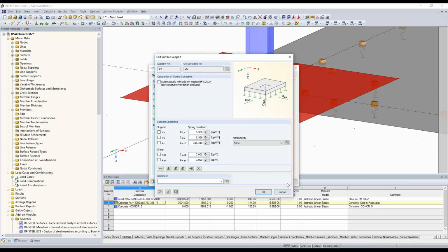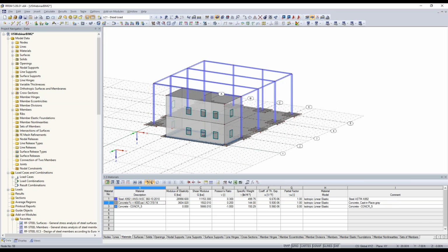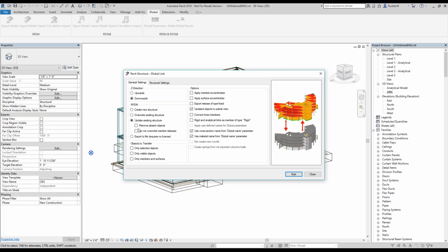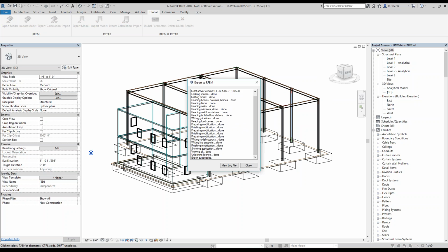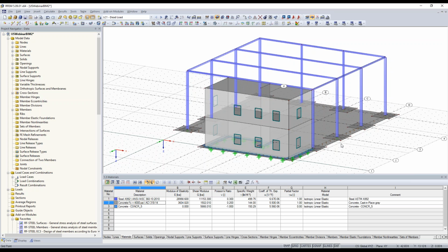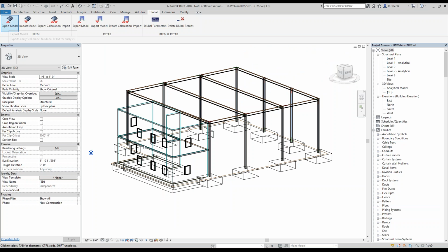Yeah? Okay, if I don't do this, I go back to Revit and I'll make the export again, but with the structural setting as they were default, nodal support into line support. Yeah? Start the export, everything is updated, and the elastic is still there because I forgot to do one thing, because I forgot to remove the absent objects, which are those ones.